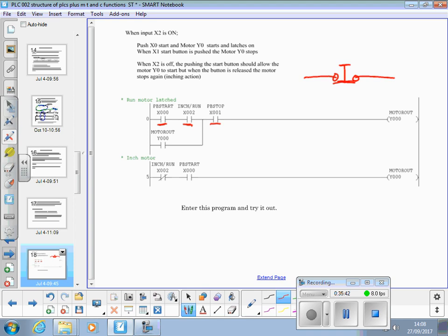The input is on when you haven't got your finger on the button, and then it turns off when you push the button. That's safety circuit standard, fail safe. If the wire falls off the switch or the switch is faulty, the machine stops or you can't start it.